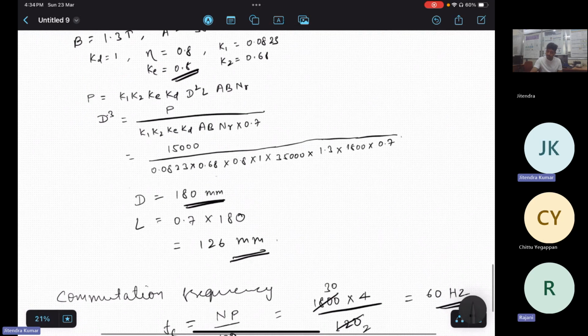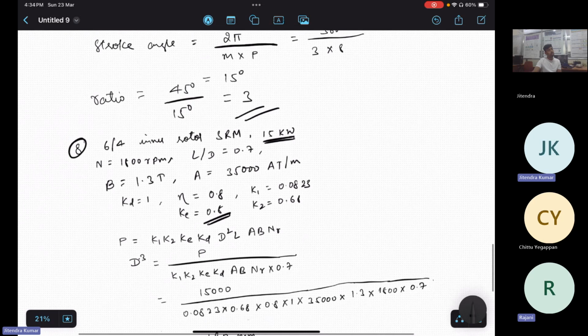And I have one more question, sir. There is one more expression, N P by 60, where P is the pole pair. No, the correct equation has only the number of poles. Okay, sir. N equal to 120 F by P.